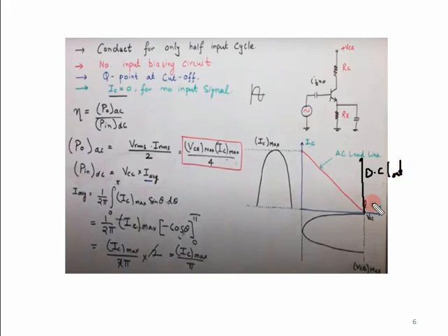So the DC load line should actually intersect the Q point, and the property is such that it is vertically above this Q point. Anyhow, the important thing is the AC load line to analyze, and for that we should first recap the properties.